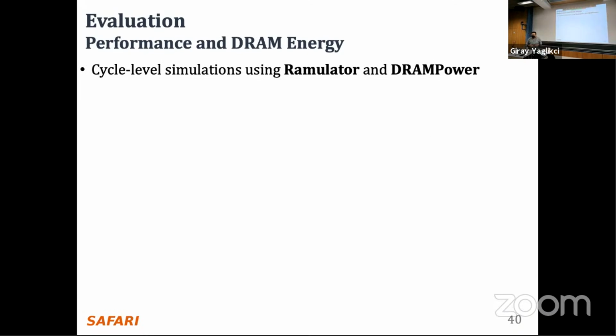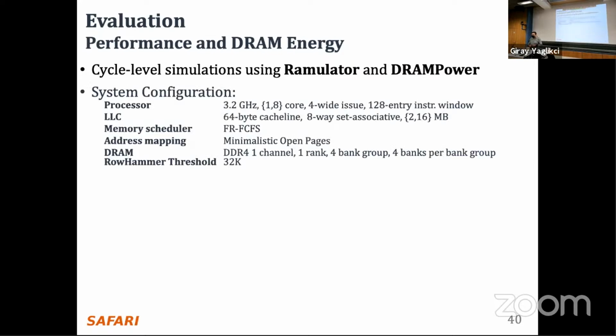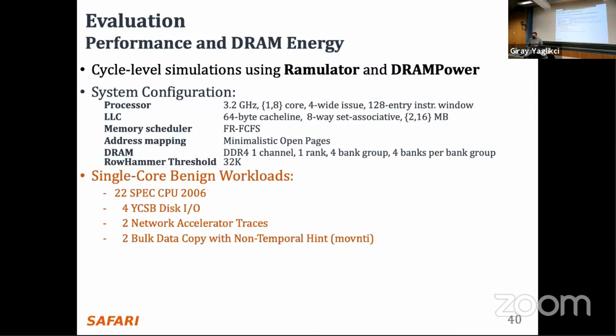As the second step of evaluation, we conduct cycle-level simulations using Ramulator and DRAMPower to evaluate the performance and DRAM energy consumption. We simulate a realistic system with a DDR4 DRAM module that is specified here. I'm not going to go into detail.